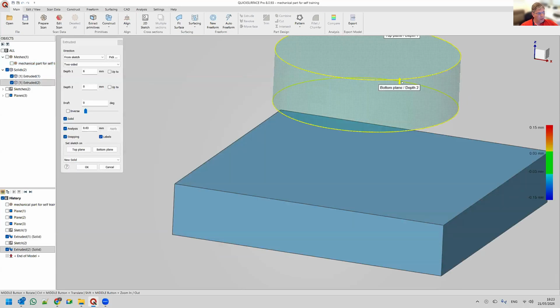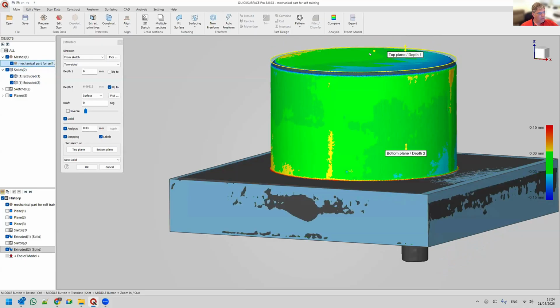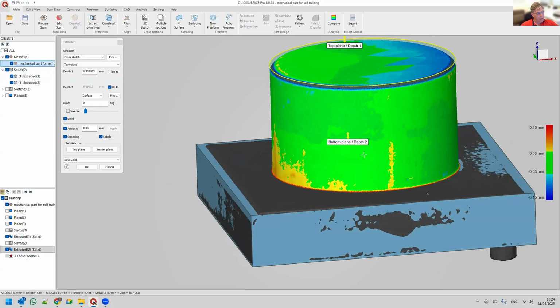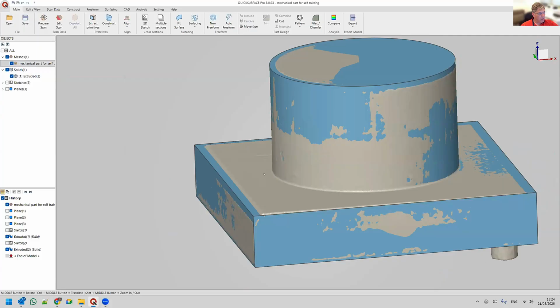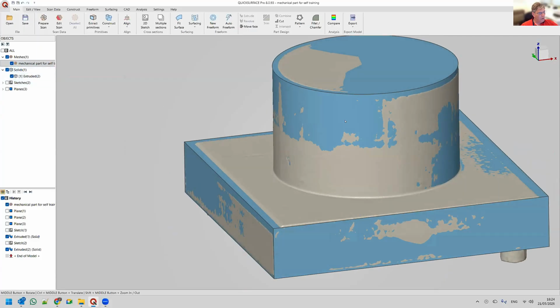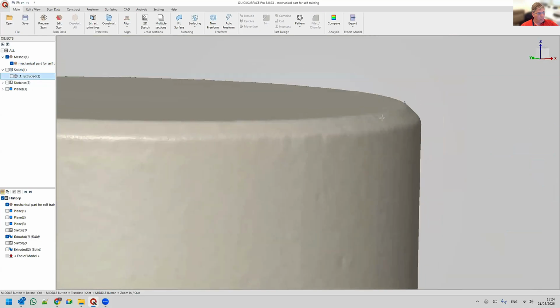So I can just extrude this. And if you remember, I can just drag this and it will just stop and snap to my body. Let's see what's going on at the top. I can just pick this because the snapping is on and I can recreate. Like in any CAD package, I can just go and combine the two solids and press OK. We created our first solid here, but let's finish our job and see what's going on top.